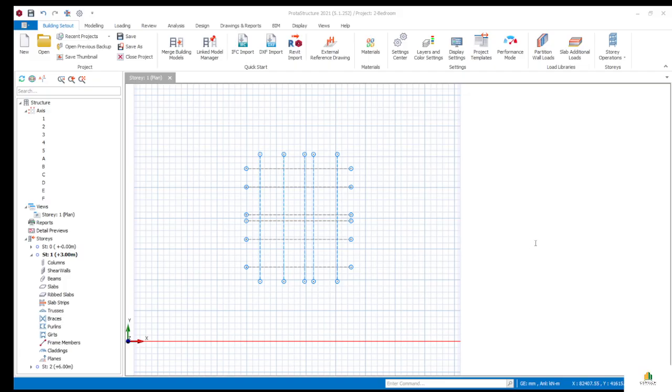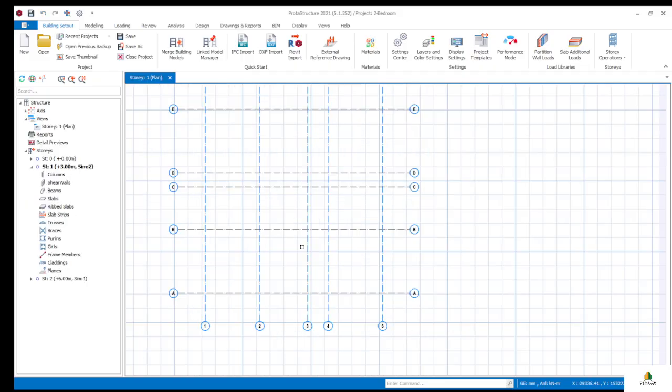So let's say the foundation depth of this one, let's choose 1000, because we are not designing anything, we are just modeling, showing how you can place your columns. Then label F, let's leave it like this. Then click OK. The moment you click OK, it will give you a warning that says this and the previous processes will not be undone after this step. Do you want to continue? Click yes.